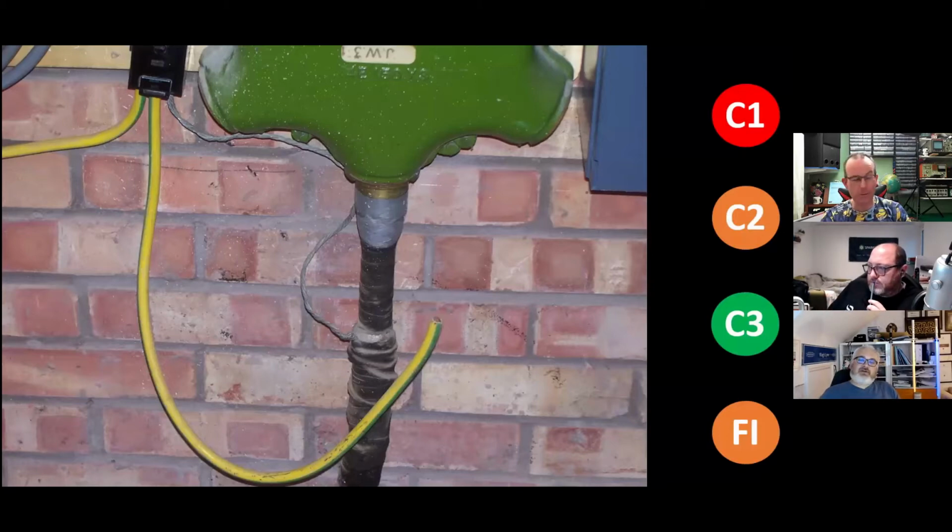So it's a valid point, Mr. Casey, and one thing that Mr. Casey needs to realise is there is now a risk assessment for cutout changes, and if it is a metal one and it is not leaking pitch, or there is no signs of thermal damage and there is a sufficient earth connection, it will be left.